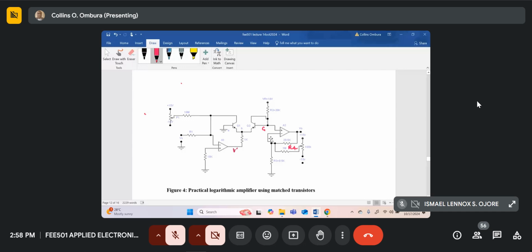If you look at the output circuit alone, whose output is V0, if you have a potential V at the inverting input of A2, this potential will send a current down through R3. And that current must have come from V0 through R4. So we can write that V0 is V plus the drop across R4. R4 is this 29.5K.